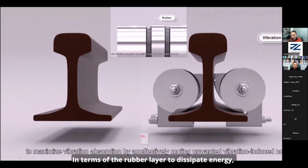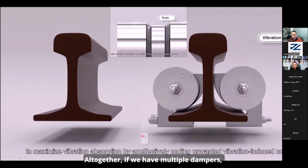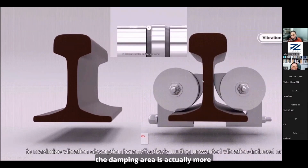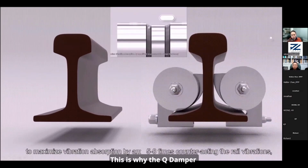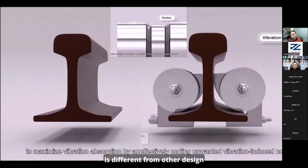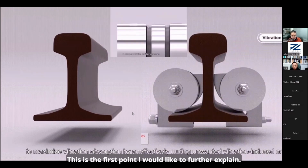In terms of the rubber layer dissipating energy, the area is very large. Every surface has this area. Altogether, if we have multiple dampers, then the area is actually more than the wheel surface area, and we have higher vibration amplitude to dissipate the energy. So this is why the Q damper is different from the others, because they do not have a rubber interface at the interface with the wheel. This is the first point I would like to further explain.